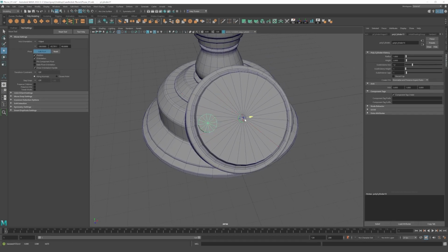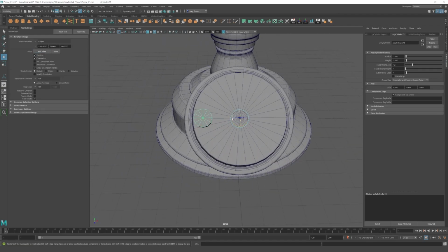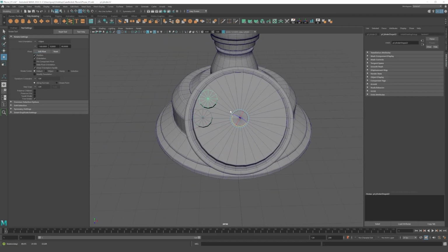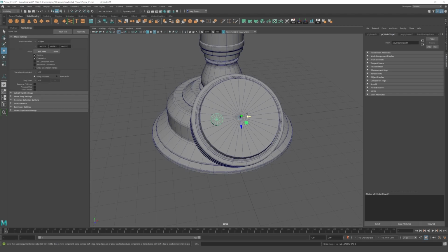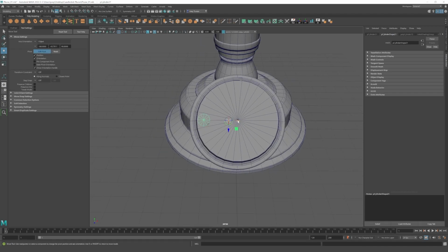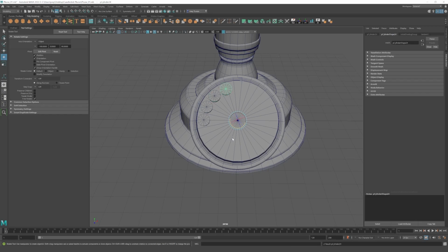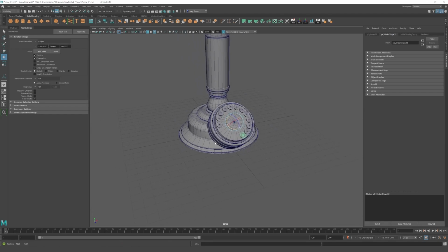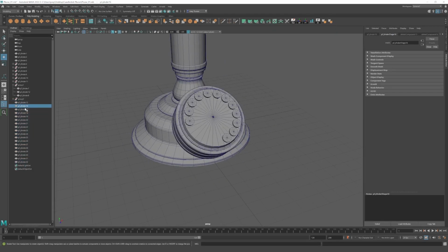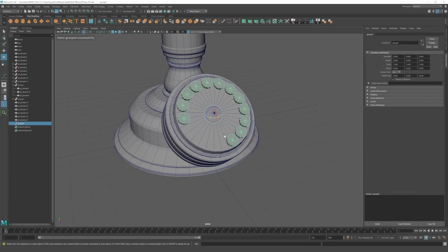And I'm going to scale that nice and small and play around with the shape until I find something I'm happy with. Now all I'm doing here is just changing the pivot point to the center of the cylinder that's below it. That way when I rotate them around, it's going to be correctly in the center of that shape. So here I'm just scaling it a little bit smaller than the previous one. I'm repositioning that pivot point, and then once I press Ctrl D to duplicate it, I'm going to give it a really nice tight space, and then I can press Shift D to redo that move over and over again until I have all of those buttons around the outside of that cylinder. And once I'm happy with that, I can select all of those cylinders, combine them into one object, and then I can just boolean out a hole into that cylinder.